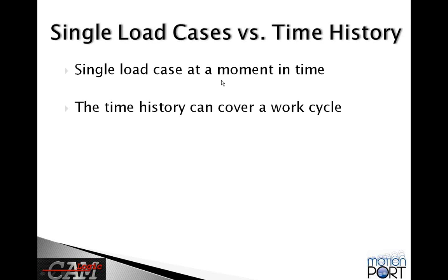In other words, you can set up the mesh and all the boundary conditions and so forth, and then just introduce a number of discrete single load cases. And you may be able to determine that by looking at plots of the loads and picking out some of the peak values. So then maybe look at half a dozen different load cases or whatever is appropriate for the work cycle that's being looked at, that can be done. And again, FEMAP supports the setup of all the load cases so that you're actually running one simulation, but then you have a whole set of outputs to review for the different load cases. So that's a very efficient process.